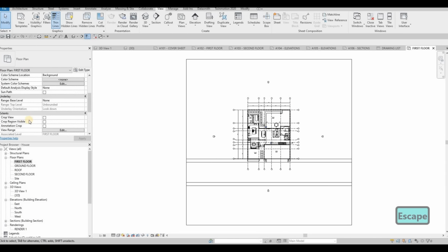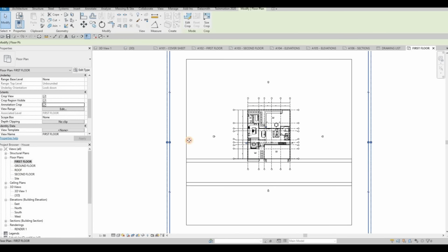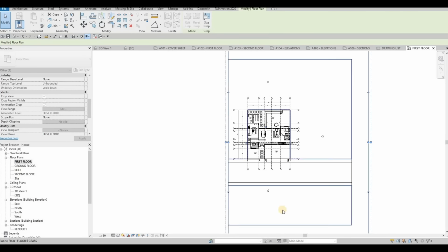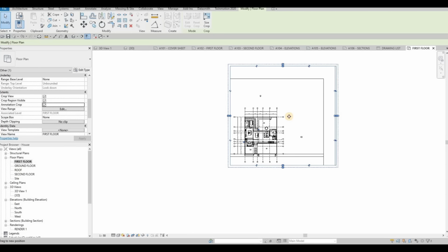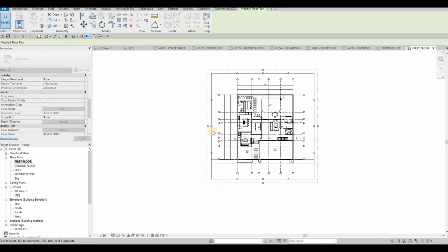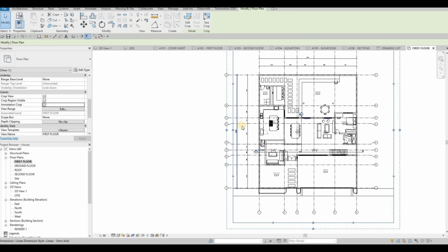So to crop it, you need to go to your properties and then extend. I usually check all of this and then click apply, and then we have this window right here that we could crop our image. And if you want, you can always cut or you can crop this, but if you notice the grid lines, you cannot crop that, so it will follow along.